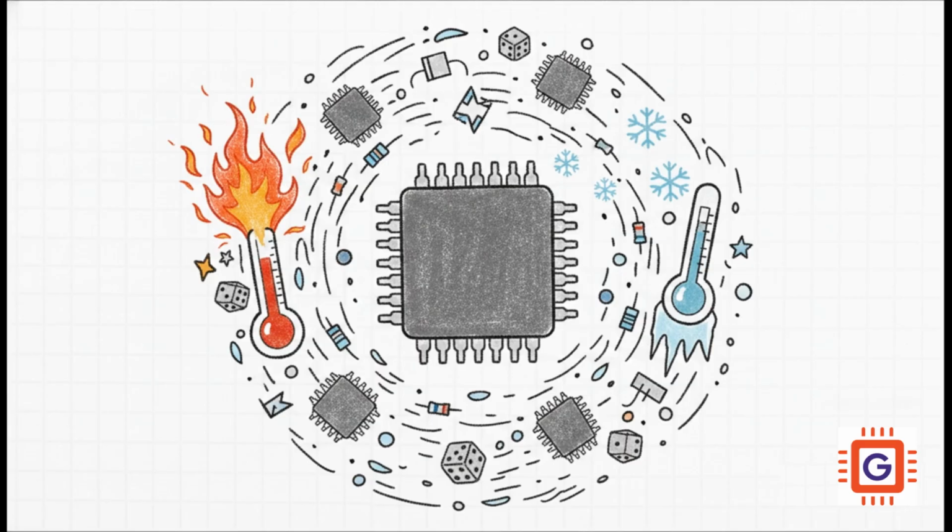We're talking inside the blistering hot core of an AI data center, or out in the absolute freezing vacuum of deep space. Plus, you have to factor in physical manufacturing tolerances, because no two transistors are ever truly identical at the atomic level. HSPICE tests all of this using Monte Carlo simulations. It runs hundreds of automated iterations that randomly fluctuate those device parameters.